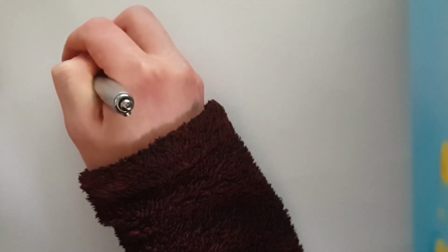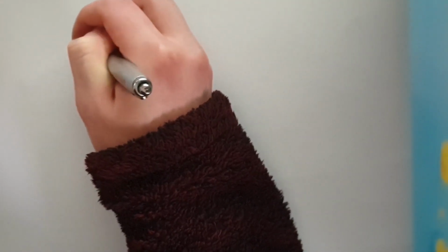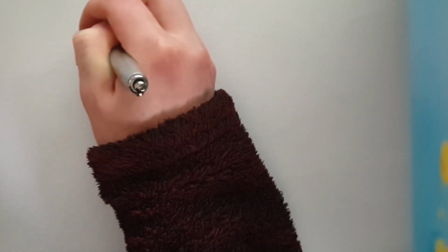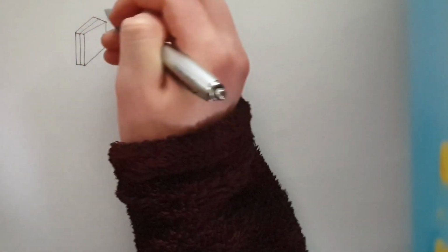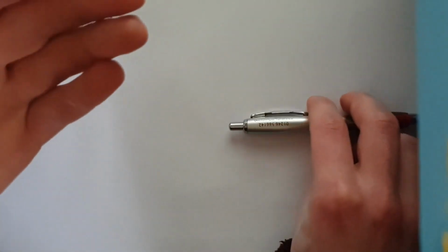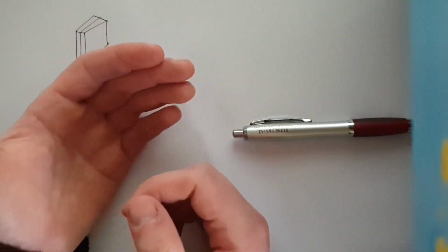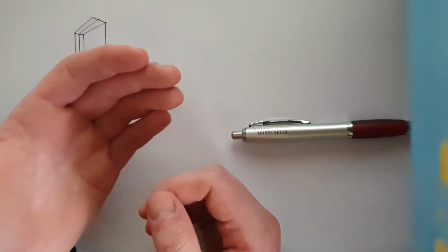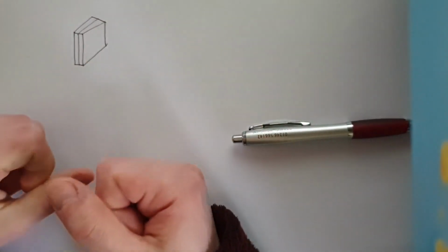You've got one layer here, and you've got another layer there. So a good way to think about this is what happens when you've got one layer on top of the other. Well, you've got heat which is trying to get through one layer. The resistance of both of them put together is going to be the same as adding those two layers together.